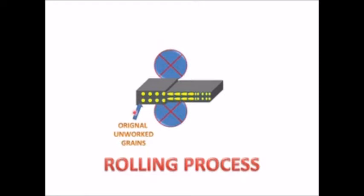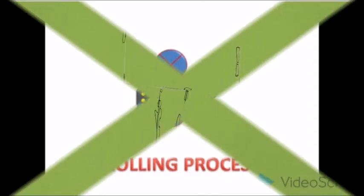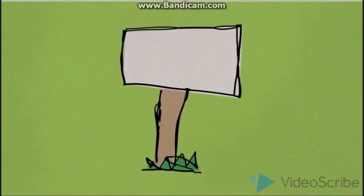These original unworked grains are changed into elongated grains and refined grains, and the thickness of the metal plate or ingot will decrease by the rolling process. So the rolling process will decrease the thickness of the ingot and refine the grains of the plate or ingot.